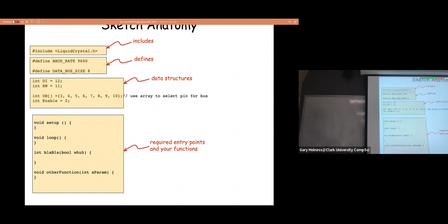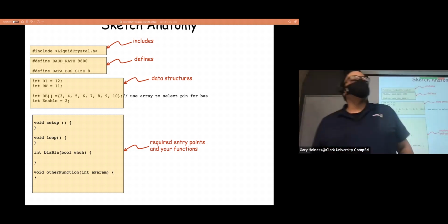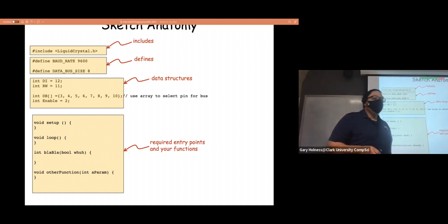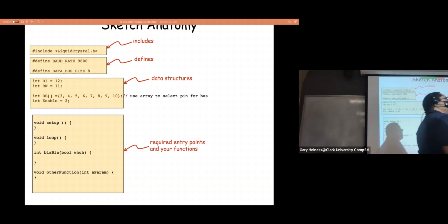And so one question that we had is, can we use variables? Yes, you can for things that could be defined. But the difference is when you use variables, there's overhead for your runtime image. Variables take up space, whereas number sign defines do not, because the preprocessor does a find and replace with the defined specifications. Any questions about this?